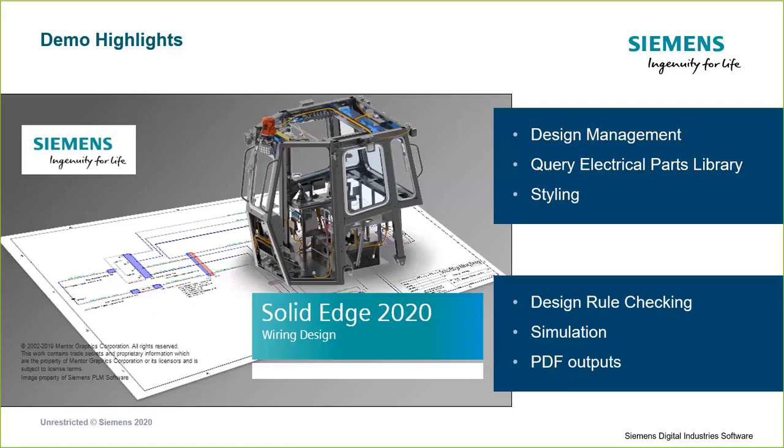You are able to do that by studying with the ability to simulate in the Solid Edge wiring design. And in addition to the PDF outputs from both the wiring design and harness design, there are tables and wire lists, etc. So you have everything you need, and it's all generated from the content inside that electrical wiring design application.